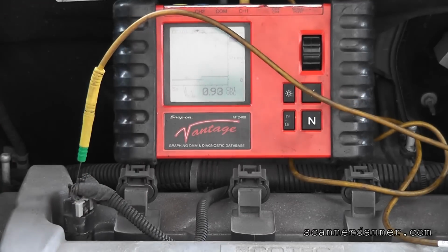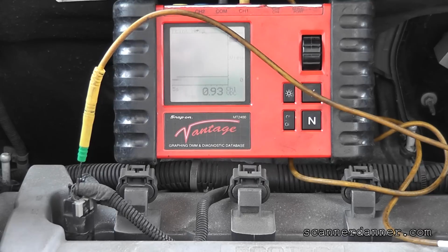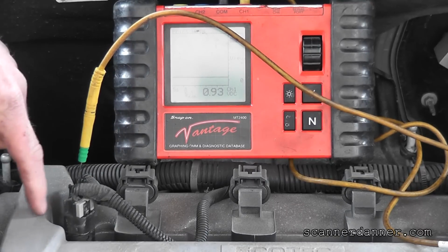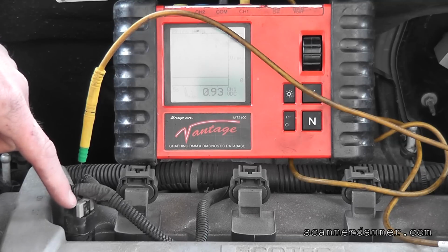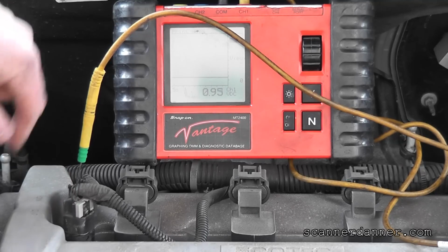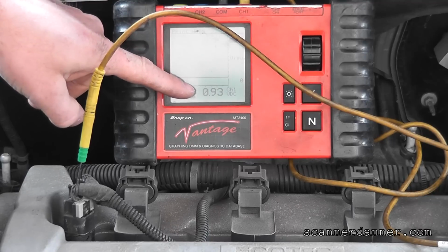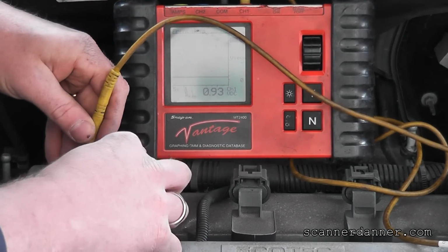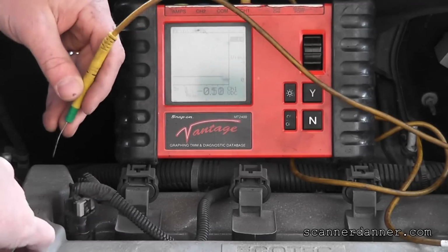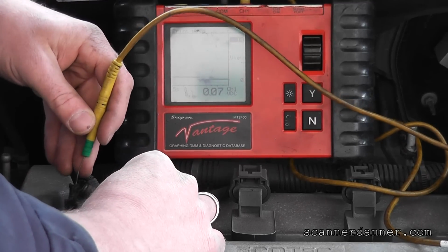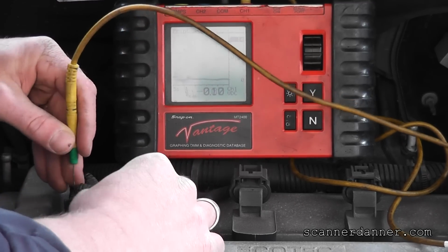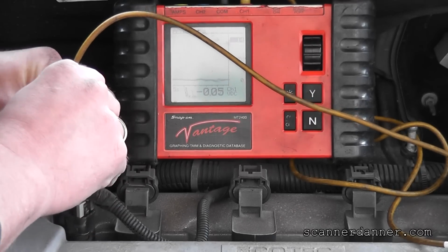There it is. A nice thing here too, on this car we have two of the same solenoids, two of the same circuits. We know the intake side works. So I'm going to do a quick measurement over here just to see if that's a normal voltage or not, this 0.93. My guess is it's not, and that we're seeing an elevated voltage because the solenoid's open, although it could be wrong.